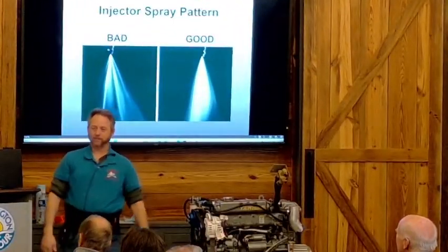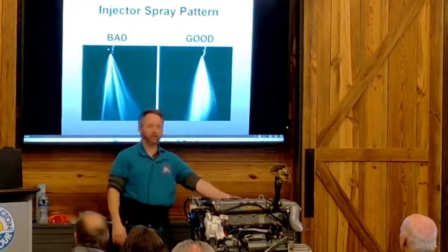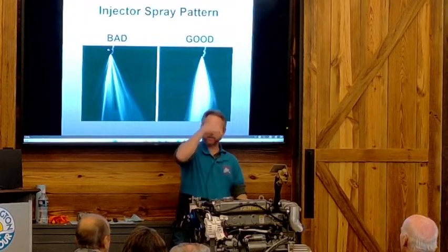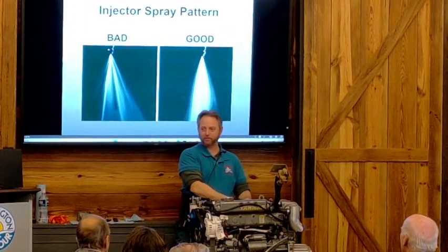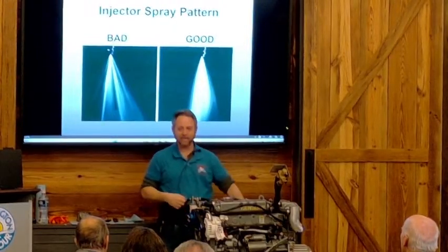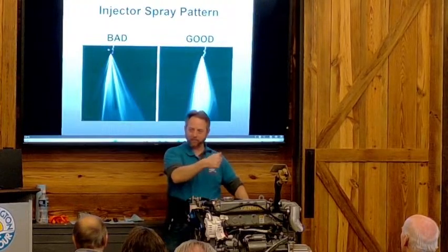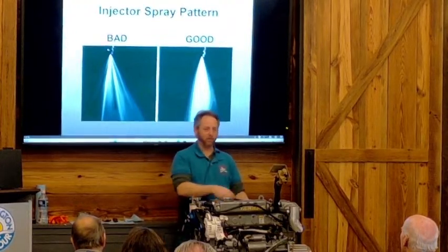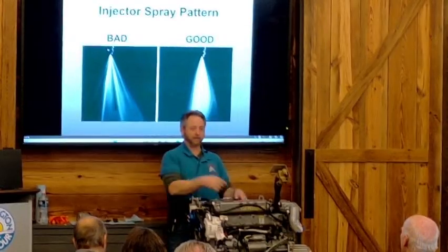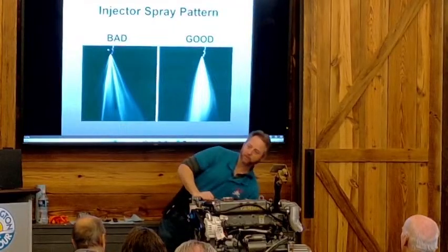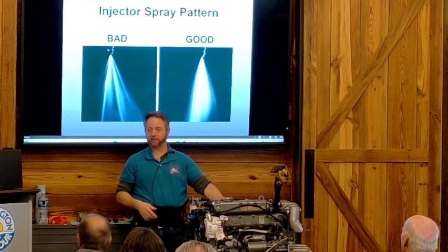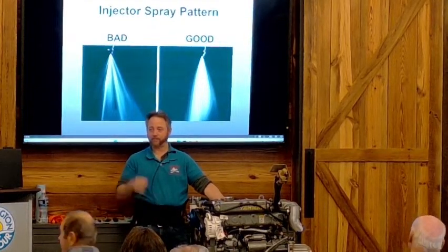What's your preference? My preference is this tube right here that this dipstick's going into is a pump out tube. You don't send the tube down the oil tube. You go over the top of it, outside of it. Now there is a tiny little hole drilled at the top of it. You just have to make sure you cover that hole when you put your vacuum pump on it. Because this dipstick goes to the very back corner of the oil pan, you're going to get an extremely good oil change by using that dipstick. There's no reason not to use that tube.